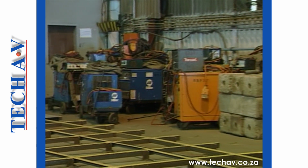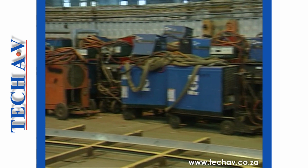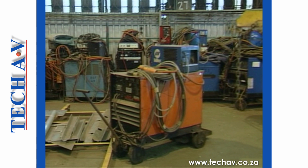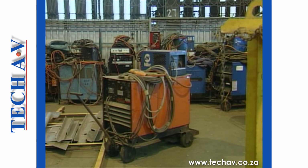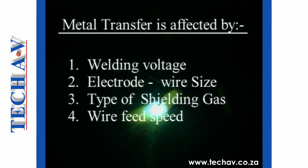The modes of transfer so far mentioned, namely dip, globular, and spray, can be achieved using most conventional constant voltage MIG/MAG welding machines. The four main factors affecting the type of metal transfer are welding voltage, electrode wire size, type of shielding gas, and the wire feed speed. During Program 3, you will learn how to set your equipment to achieve short-circuit and spray transfer modes.